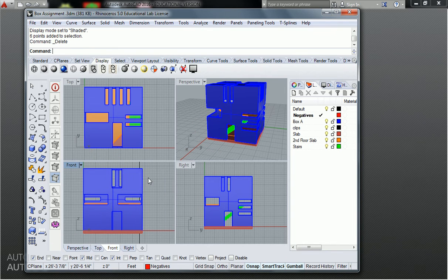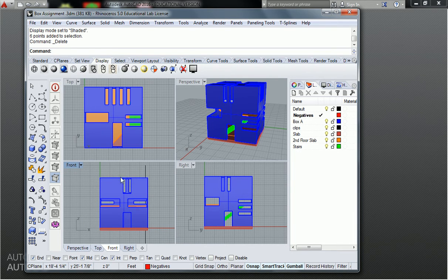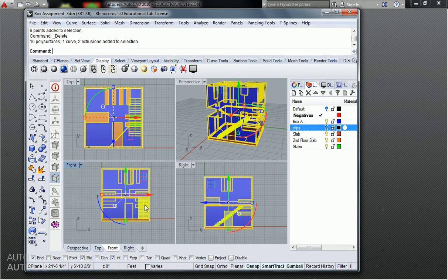But to get us ready, I'm not going to actually execute the command, but I will show you what it looks like first so that we can think ahead to what's going to make it a good workflow for us. So turn that off. If I select my object and I say, I want to take my front elevation and make an elevation drawing out of it, two-dimensionally, the command, and you guys are going to hear a lot of this command, so you can write it down if you want. Otherwise, you're going to hear it probably 10 to 12 times more from me again today. So Make2D is the command.